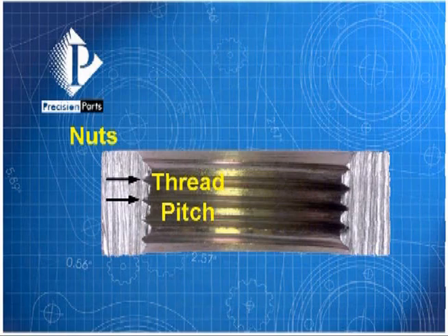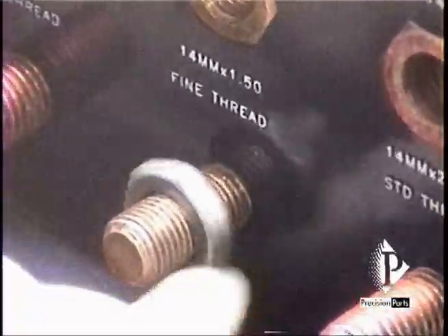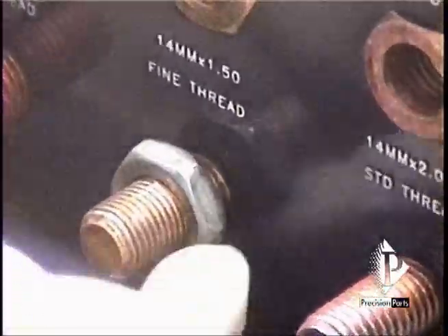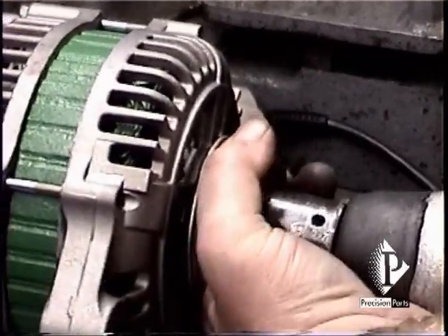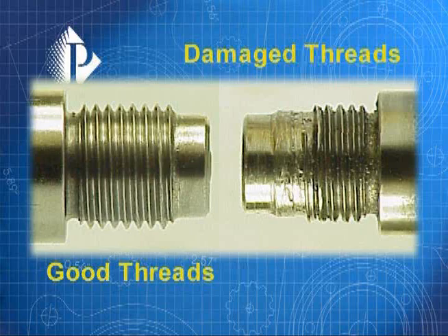It is often impossible to tell the thread pitch of a nut simply by looking. It is a good idea to get in the habit of checking the thread pitch to make certain the nut is sized properly for the application. An impact wrench can often force an improperly pitched nut on a shaft, with catastrophic results.